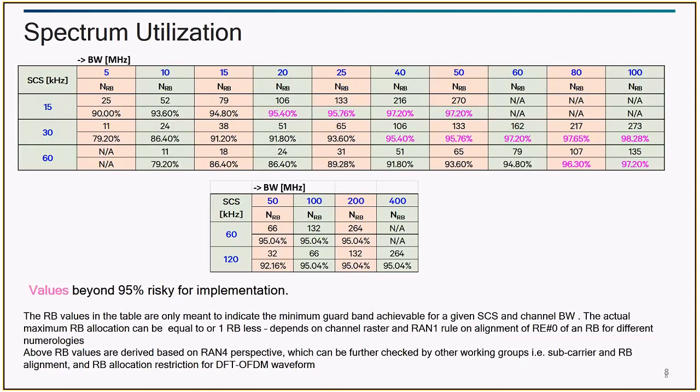But with respect to time, some reference has to be fixed, right? That is fixed. So for example, in LTE, when you go to this bandwidth, the PSS SSS is in the central 1.08 megahertz. When we come to NR, you would see the PSS SSS coming in a grid-like structure.